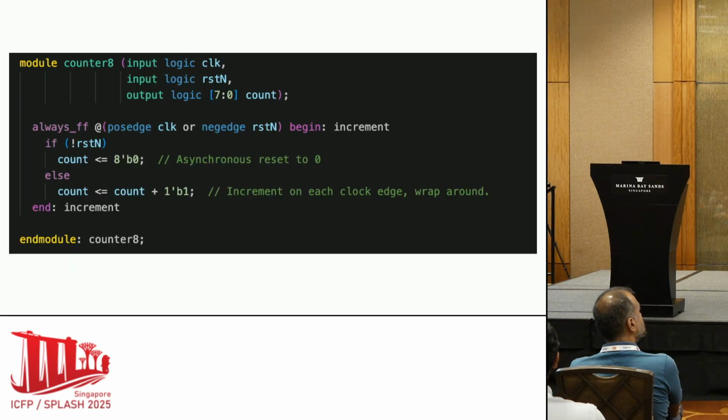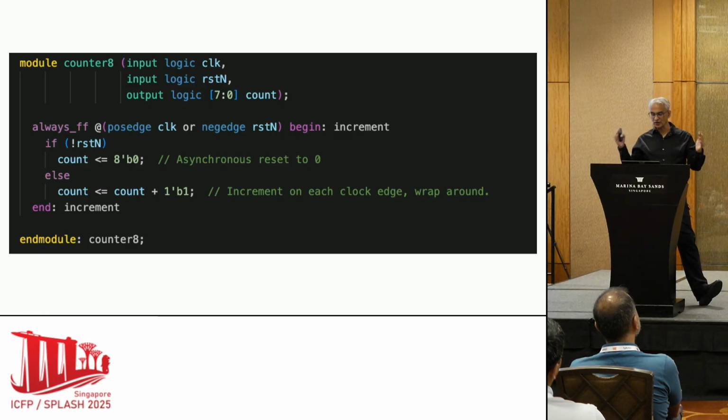But that's not actually how most hardware design is done. The main way of specifying hardware is to specify a collection of concurrent processes, each of which contains sequential code, which is algorithmically executed in a C-like manner. These concurrent blocks listen to events on wires they care about, and then they fire, potentially updating other wires, triggering other concurrent events until a fixed point has been reached. System Verilog and VHDL are really input scripts to event-based simulators.